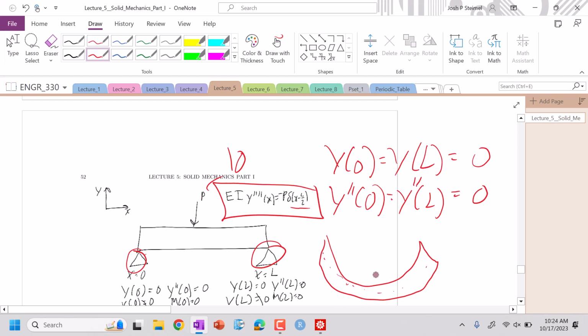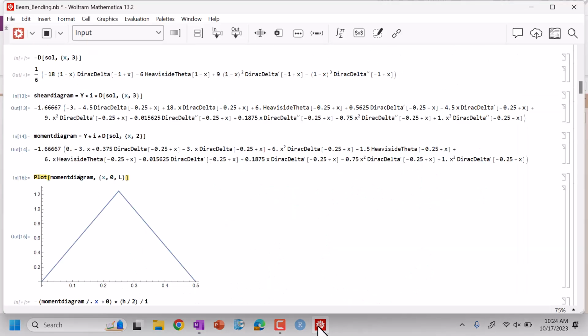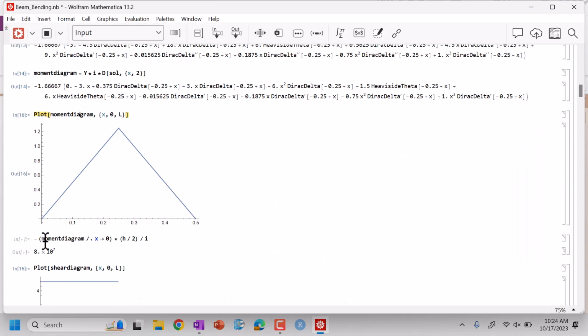And if we look at where the moment is maximized, again, we still have our y. So if I look at here, this is tension now on this side, and then this should be in compression. So if I plug in, for example, our moment is minus moment, and then we're going to set it at 0.25, the x value. If I do it at h over 2, positive, I'm in compression. If I do minus h over 2, I'm in tension. We got it. Maximum stress. So we are good to go.